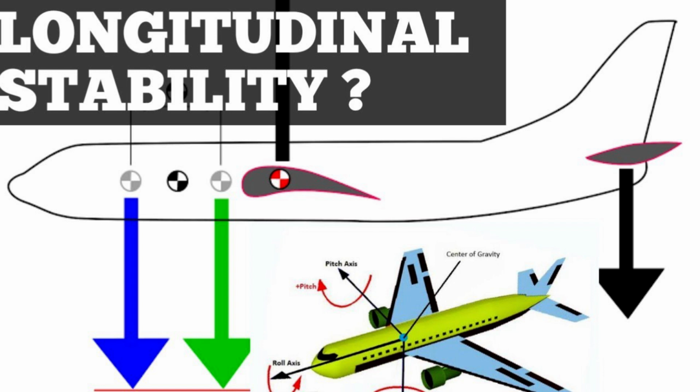In analyzing stability, it should be recalled that a body free to rotate always turns about its CG. To obtain static longitudinal stability, the relation of the wing and tail moments must be such that, if the moments are initially balanced and the aircraft is suddenly nose up, the wing moments and tail moments change so that the sum of their forces provides an unbalanced but restoring moment which, in turn, brings the nose down again. Similarly, if the aircraft is nose down, the resulting change in moments brings the nose back up.